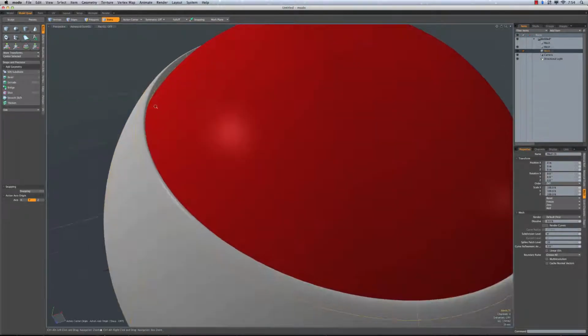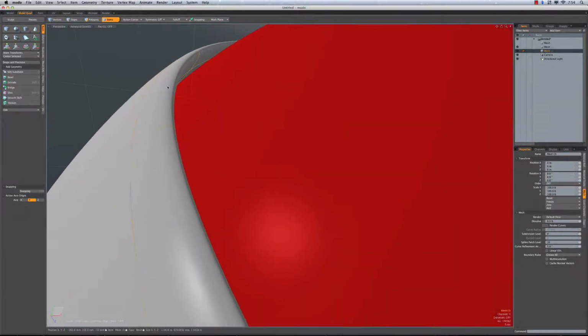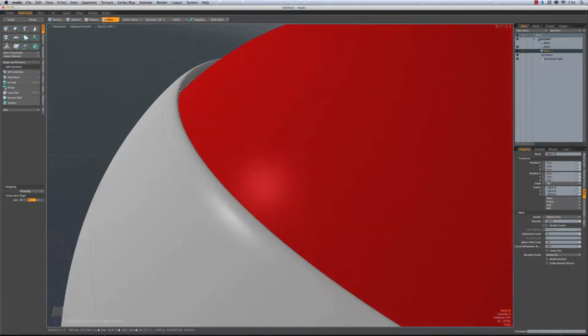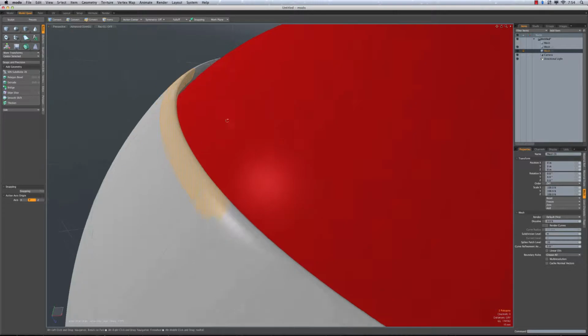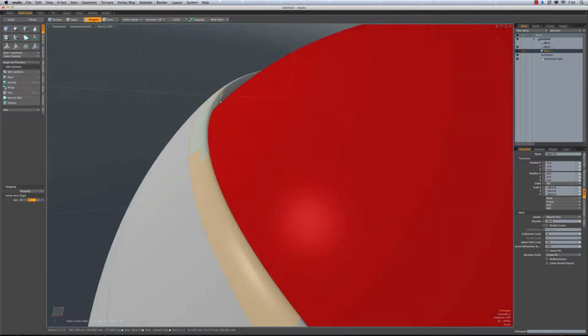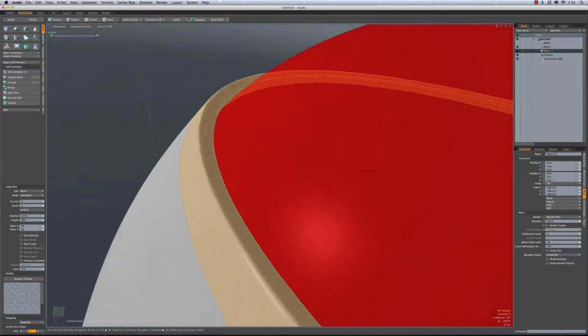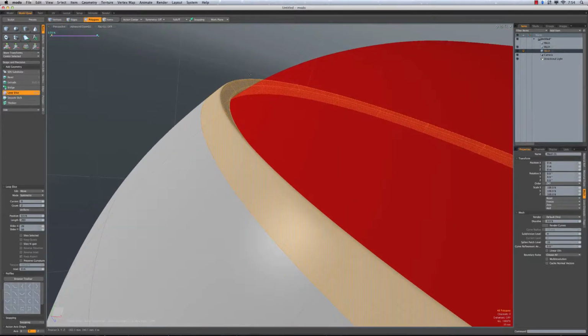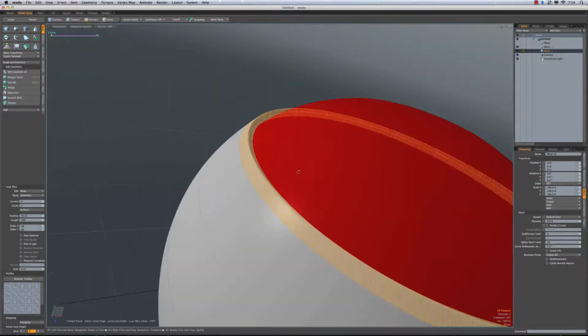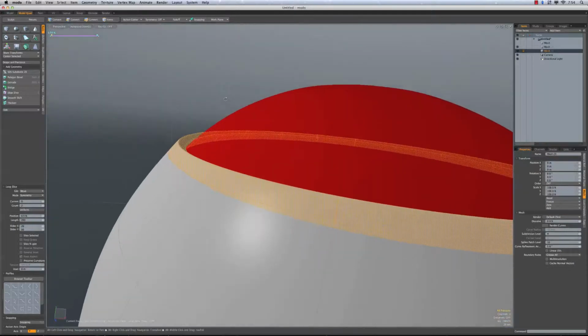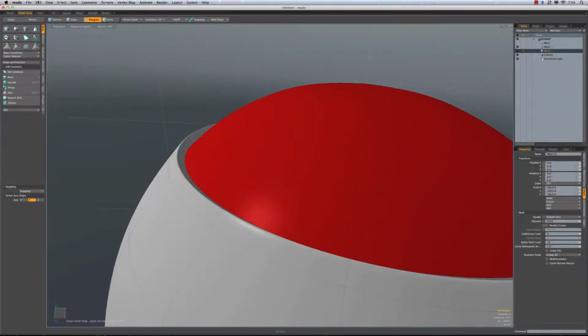So at level 4, when I zoom in here, this should look really clean and smooth. We don't have any issues here. Now we have two options for the way that we create the sharpened edge here. The first way is kind of the classic symmetrical loop slice, where we get a loop slice on either side, and those will run around that rim and create a nice, relatively sharp edge. So let's have a look at that over here in the model view.